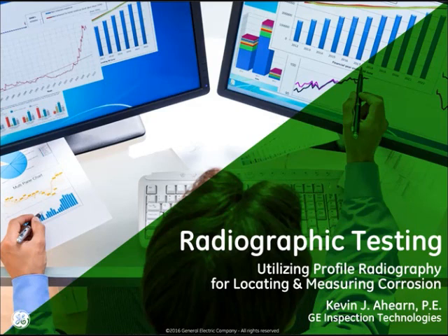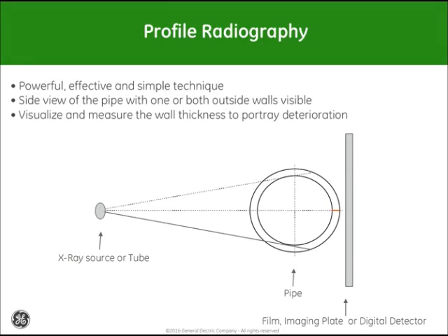In this particular case, we're going to discuss profile radiography as it applies to the identification of corrosion inside a pipe. So what would typically happen is that you would set up an X-ray source approximately 3 pipe diameters away from a particular pipe and place either film, an imaging plate, or a digital detector on the opposite side in order to create that image. Profile radiography is very powerful, effective, but also a very simple technique.